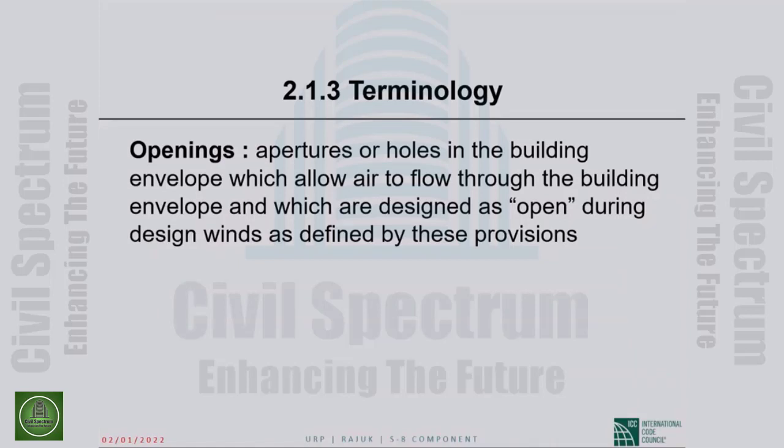Opening, this is an extremely important definition. I cannot overemphasize this. Apertures or holes in the building envelope which allow air to flow through the building envelope, and which are, this is the important part, which are designed as open during design winds as defined by these provisions.